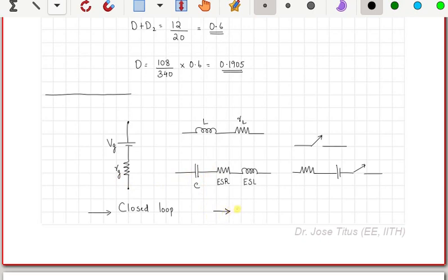The losses that happen in all these resistors and the drops across these series voltage sources will all affect the efficiency of the converter, and therefore when you design the converter for a given efficiency as well, you will have to give more consideration to these parasitic effects. So the efficiency is more affected than the output voltage gain, we can say, because we anyway have a closed loop control to operate the converter.